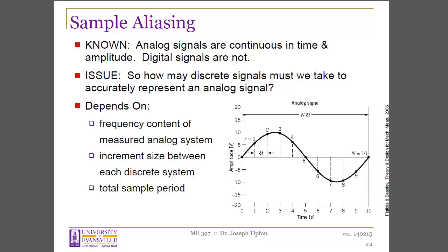Well, in that case, when you drop the car, it's going to oscillate in response because the suspension system has springs and dampers associated with it. So the question is, how often do I need to sample data from the accelerations to be able to catch the peaks and the troughs, the movement of the suspension through the acceleration? And this issue is directly tied to sample aliasing.